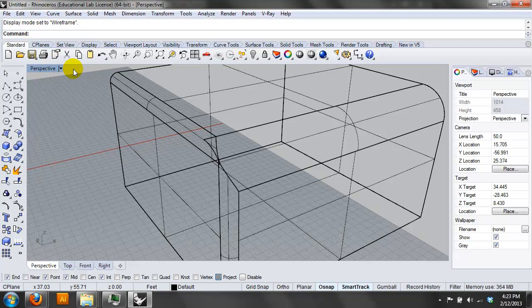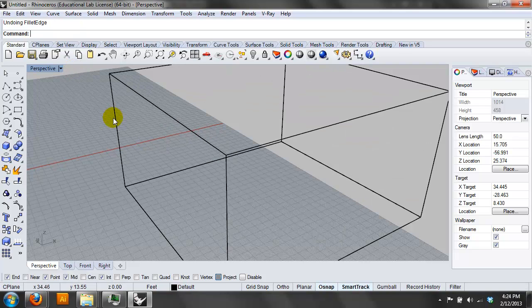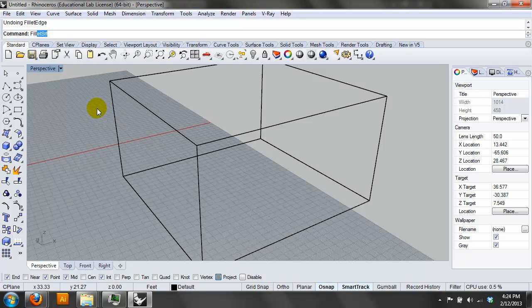Split your radius up. Well, there's actually a way to do it so that when they overlap, you trim it, and then you let the three kind of patch together. That's what I wanted. I stitch fillet edge, and when you click all of them, before you hit enter, there's a little number. Yeah, you can change the number. Click and adjust it. But all of mine seem together.